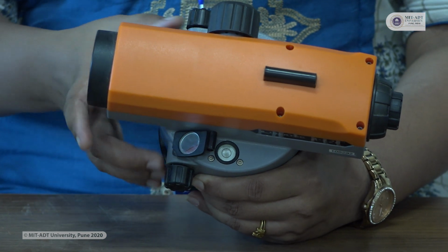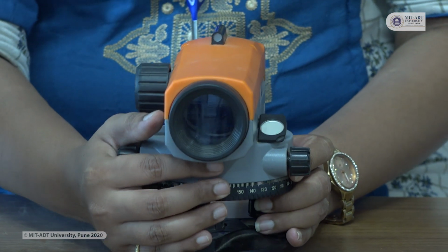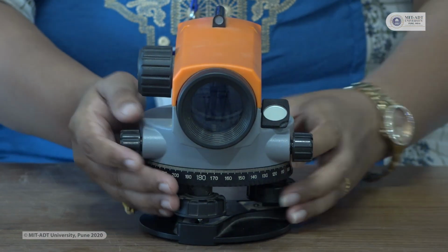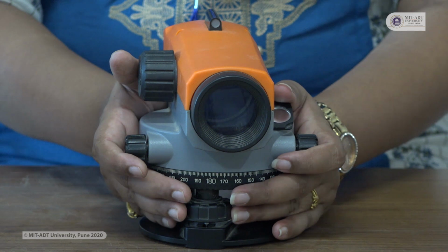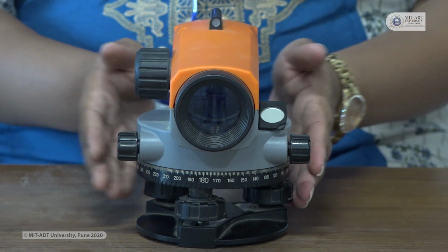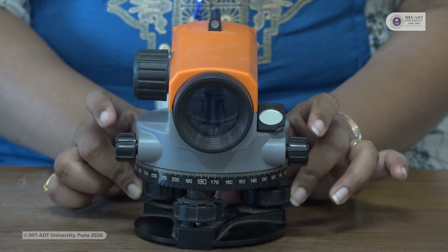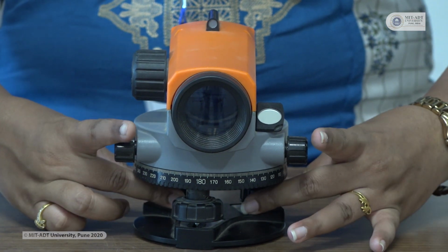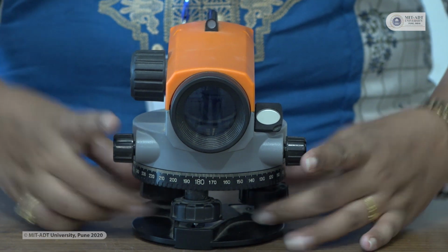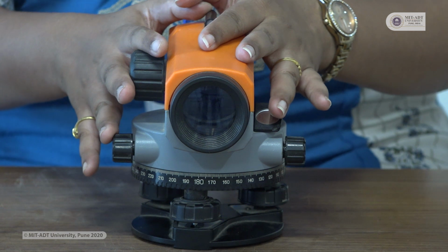By using these 3 foot screws, you can make sure that your instrument will be in level. There is a basic process for leveling this instrument. Before starting the leveling, you have to place your instrument parallel to these 2 foot screws, and then you can make an arrangement in clockwise or anti-clockwise direction. Once you fix this instrument on the tripod, then you will get a better idea of this leveling.